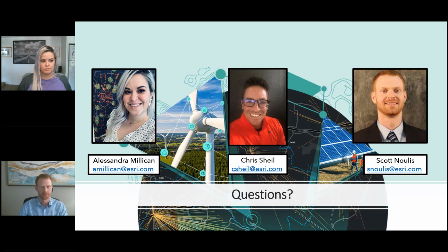Cool. How about the Suitability Modeler? Does that have to be published as a GP service from ArcGIS Pro? It can be, but it doesn't have to be. You can certainly publish a geoprocessing service. If you've got something like a ModelBuilder model and you wanted to be able to run that through a web interface, you can publish a GP service and support that either using ArcGIS Server or image server if you've got raster data.